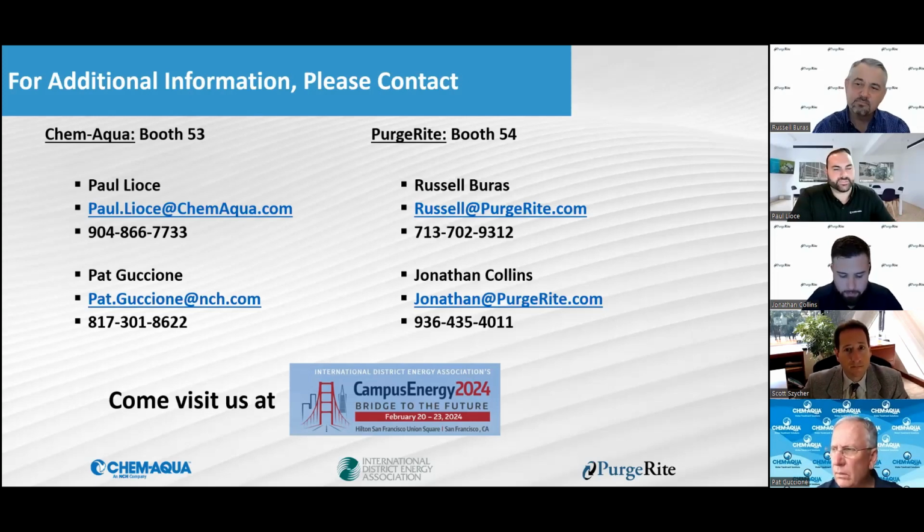So if you have standby systems or offline chillers, and you feed oxidizing biocide Monday, Wednesday, Friday, with a Tuesday for your non-ox, or whatever your schedule might be, just have those offline systems. They don't need to be turned on and run with load. We just open up those valves and allow that water to go through, so they're not sitting stagnant.